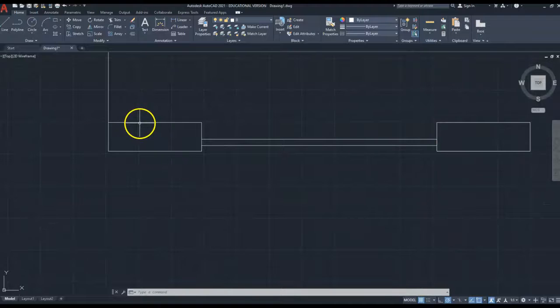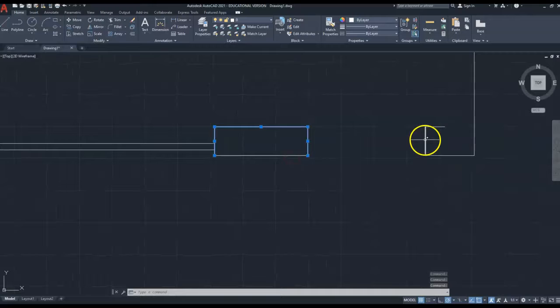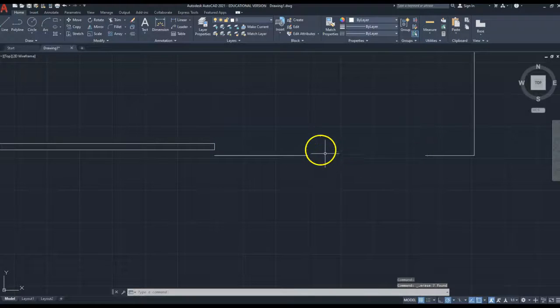I'm just highlighting these internal walls because I'm going to change this from a one brick thick wall, which is 225 millimeters, to cavity wall. Okay, so now what I need to do, this is how I'm going to do it. I'm going to select draw line, and from this point up I'm going to go 100 millimeters because that's the width of a brick, and that there is 375, so that wants to be 275.